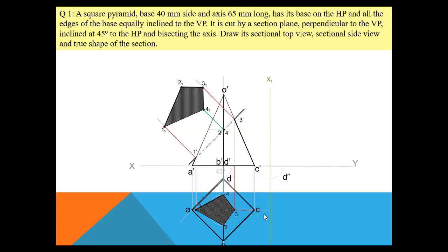Likewise, if you want to get points A and C over here, how will you do it? Just extend this horizontal projection line up to the vertical reference line x1 y1, then take this distance from this point to this point in your compass, keep your compass at this point and complete a quarter circle. That particular point will be nothing but point A double dash as well as C double dash in your left hand side view.